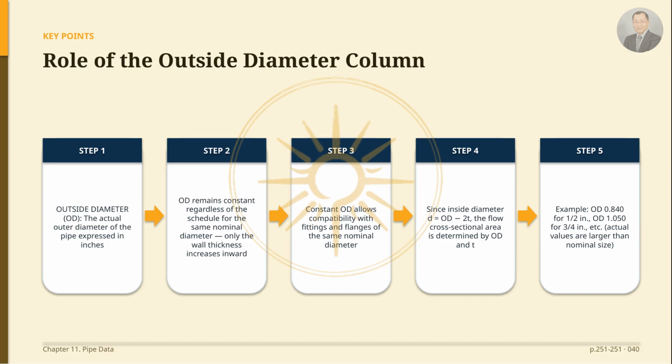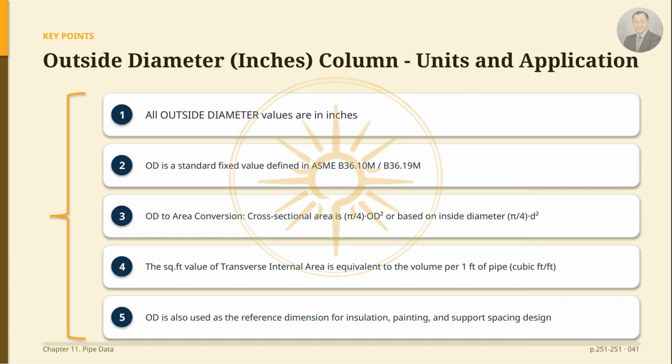Please refer to the remaining detailed figures in the table during design, and I recommend verifying the nominal diameter first, and then reviewing the flow cross-sectional area and component compatibility based on the corresponding outside diameter value. I will explain the units and application of the outside diameter column.